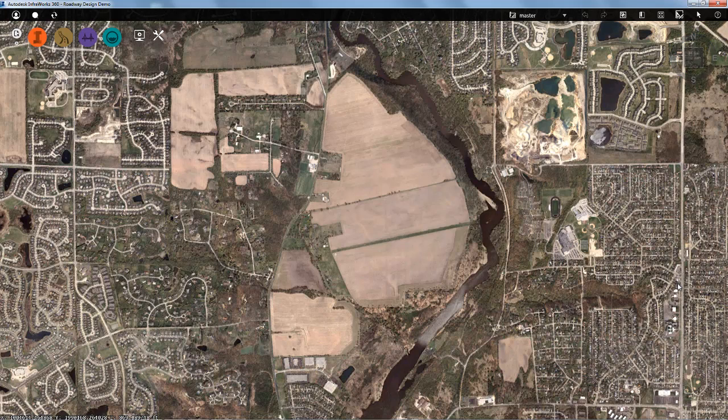Knowing this, as my initial proposal, I'm going to explore connecting from the end of this existing dead-end street along the existing roadway here and then into the open space. Now, to reach the open space, I will need to cross another main road at this point. From here, I will run my new road along the natural break in the property over to the riverbank. We will then cross the river and meet up with the existing road on the other side.